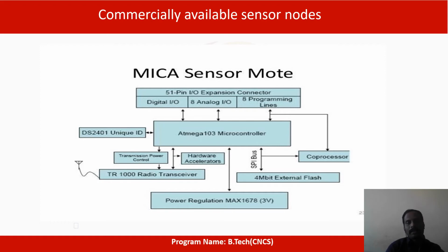The next field is analog I/O, that is analog input and output. The signal from the sensor measures the surrounding natural factors such as temperature, pressure and flow rate, which are analog signals, and most control actuators move according to analog signals. Only digital signals can be handled by computers.